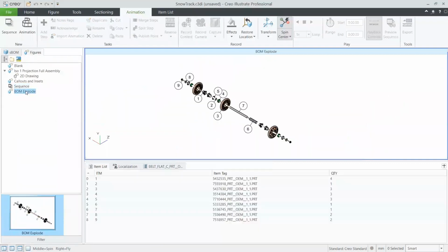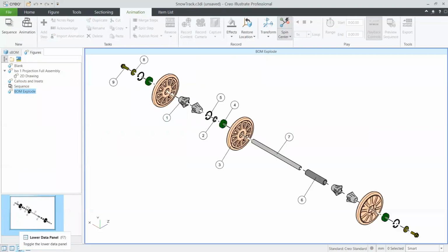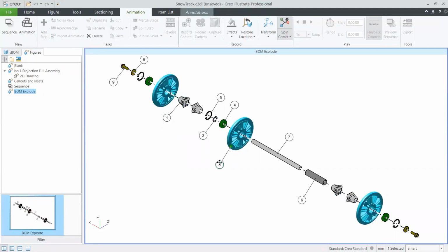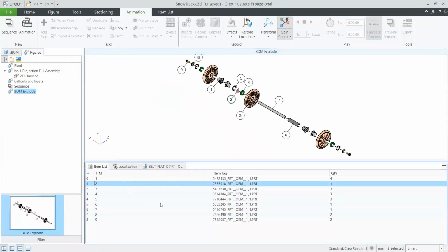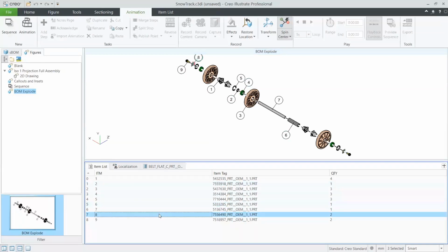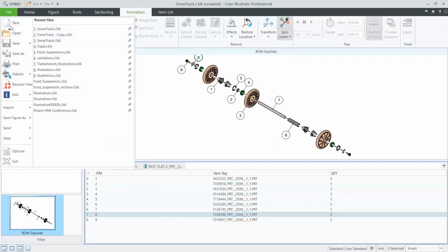All right, last view that we have down here is a more traditional exploded view. It's again still going to be very essential to a lot of people's processes. This is going through and showing all the different parts here that were within the subassembly. This is also a bill of materials view. So Creo Illustrate has the capability of attaching these different annotations to each of these parts, something that you could consume in a parts catalog viewer, or you could simply select on the parts that you're working with. They highlight right along in that view. And then you could see some of the tags that we have along with that in the table of information that's tied to that illustration.